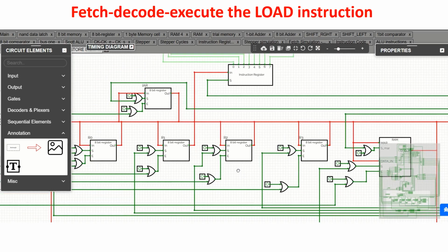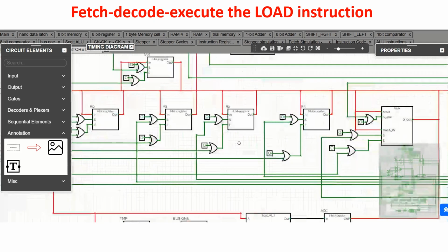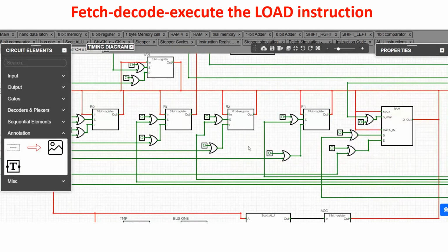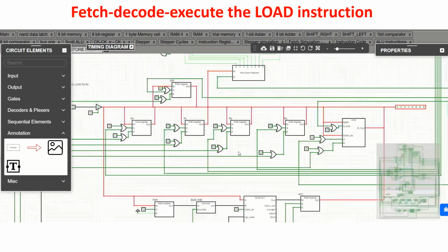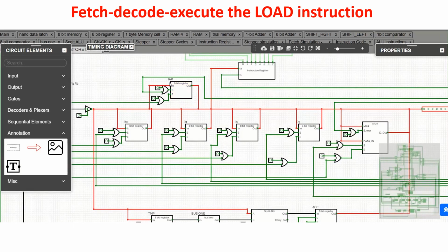If our simulation goes well, we have to find this byte in register 2, because we are running a load simulation, and we have to find in the IAR the number 1, because we have put here the address 0, and in the fetching phase we have to increment the instruction address register by 1 in order to point to the next instruction.